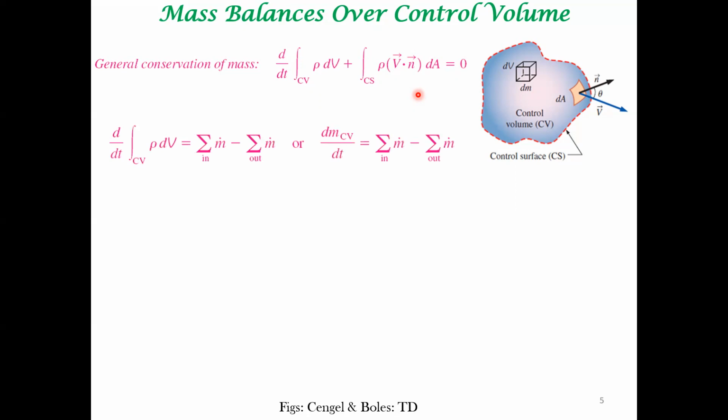We can also think about the mass flow. We're implementing this. This is the term here. These two come from implementing this term, right? It tells you the incoming mass flow rate and outgoing mass flow rate. So the change in mass per unit time in the control volume can be related to the incoming mass flow rate and the outgoing mass flow rate.